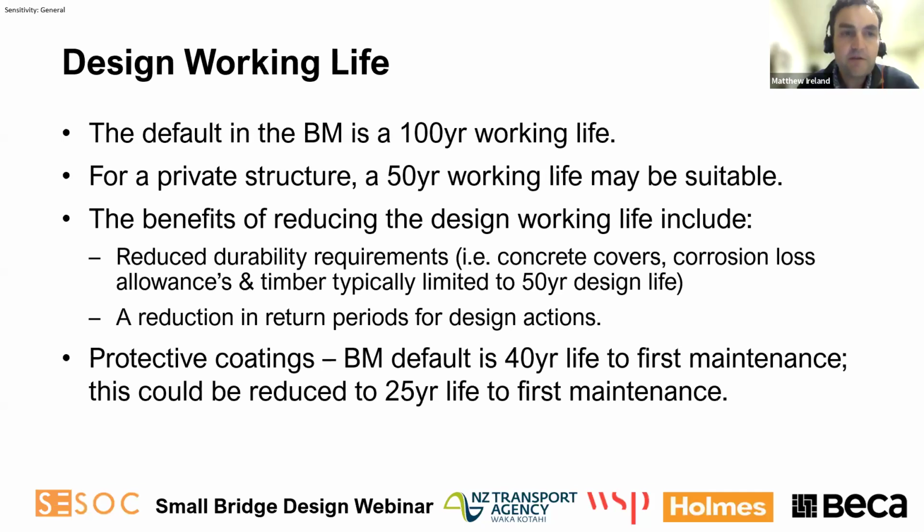So now just to get into a bit more of an overview of some of the specifics of the bridge manual. Again, we touched on this earlier, that the default in the bridge manual is a 100-year design working life. For a private structure, a 50-year design working life may be more appropriate, to make some savings. The benefits of reducing the design working life include reduced durability requirements.